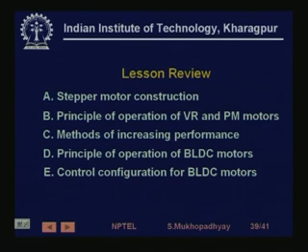So coming to the end of the lesson, we have seen stepper motor construction, principle of operation of variable reluctance and permanent magnet motors, and methods of increasing their resolution and speed of rotation by slewing. We have also seen the basic principle of operation of the BLDC motor, and we have seen one control configuration of BLDC motors and seen that it is just like a DC motor except for that PWM switching which creates the stator phase to rotate.